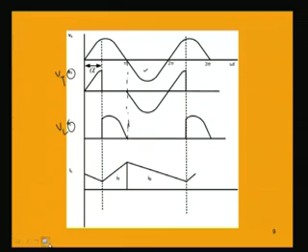So, this rectified output is half wave rectified output, and it is not present during the negative half cycle. That has been achieved by using a flywheel diode, which is bypassing the load current in the negative half cycle.